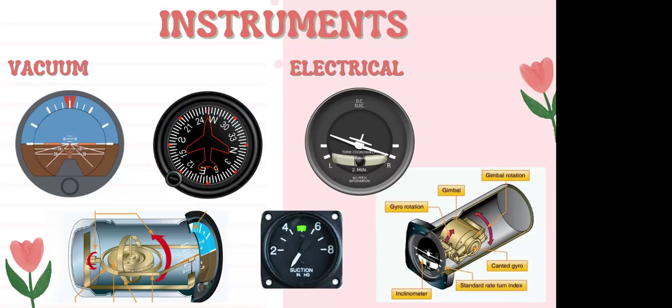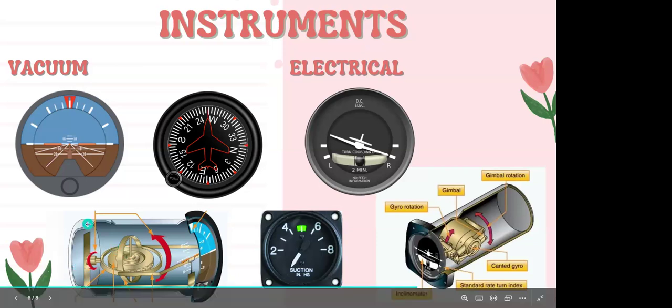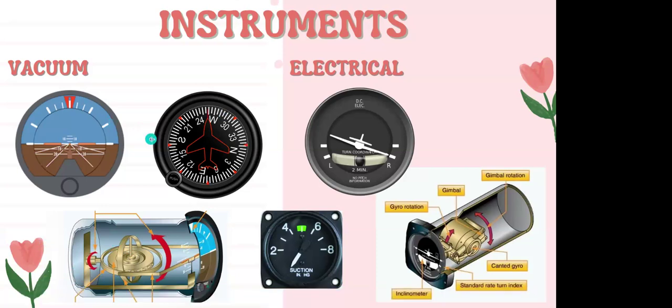And when I say vacuum driven, what I mean is vacuum pump. So attached to our engine is a vacuum pump. They call it the engine-driven vacuum pump, which makes sense. And the vacuum pump does exactly what it sounds like it does. It creates a vacuum in these two instruments. And the reason it does that is to spin these gyros. We have both of these instruments here, along with the turn coordinator, which we'll get to in a minute, are gyroscopic instruments. So, and they're vacuum powered.